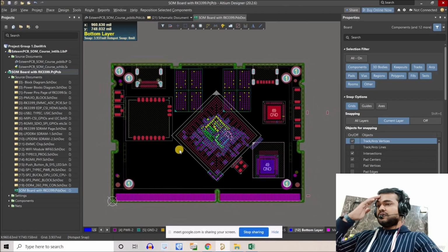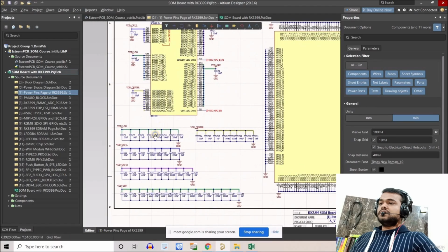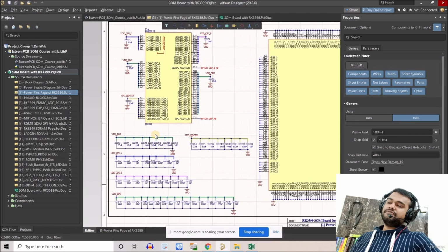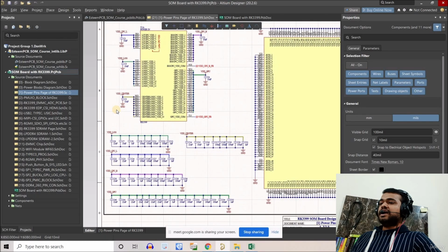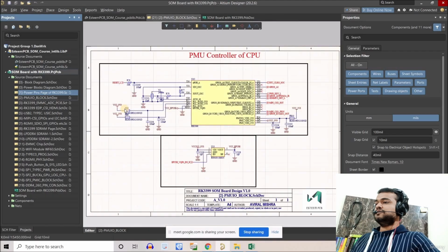Apart from those, I've added one more point on the assignment, and that was you have to assign the differential pair net classes as well as the net classes to club all the similar kinds of impedance, all the tracks which have the same impedance. You have to just club those. So I just did that for you, and if you want to try that by yourself, this whole schematic or this whole project can be used as a reference, and you can see where you are making some mistakes and like that.